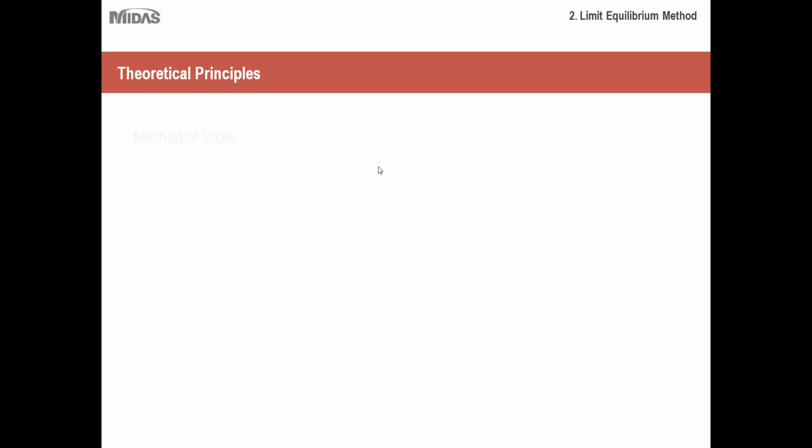Okay, so let's talk more about the theoretical principles, more specifically the method of slices. So the first thing to remember is that it's based solely on statics. That's something that a lot of engineers, when they first learn about the limit equilibrium method, are surprised about. Because what typically happens is they'll start using these programs without understanding the concept behind it. So when they realize that it's based purely on physics, it's a surprise to them because it's very simple and straightforward in that respect.